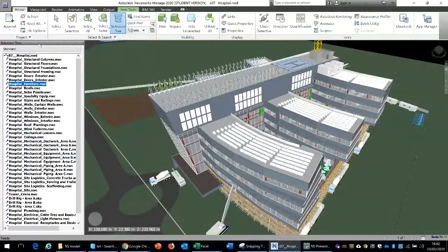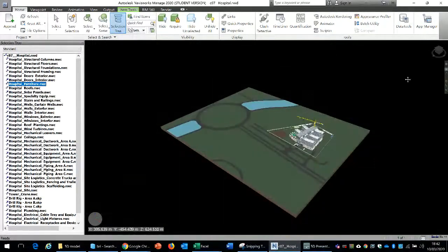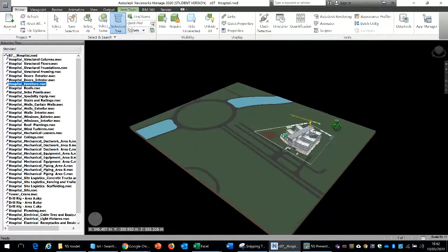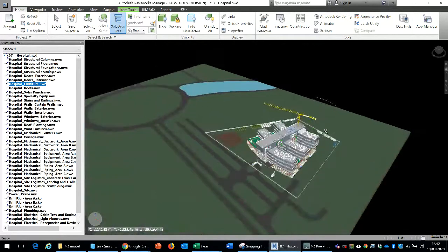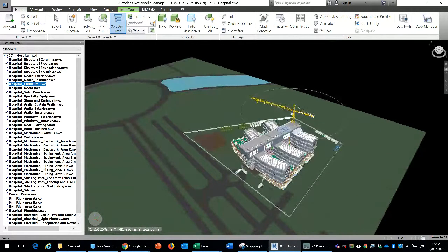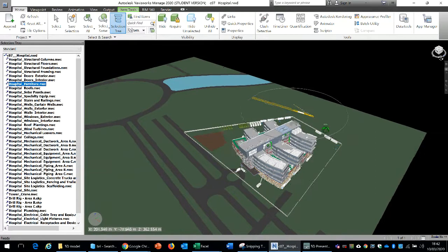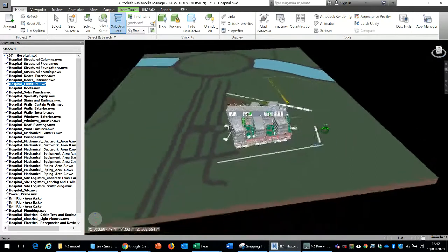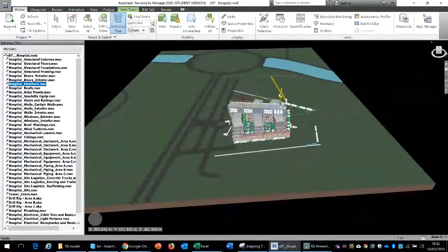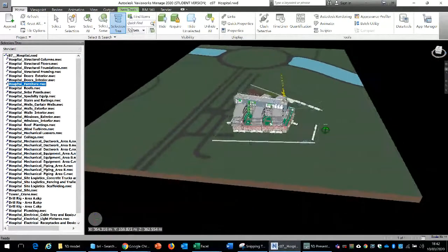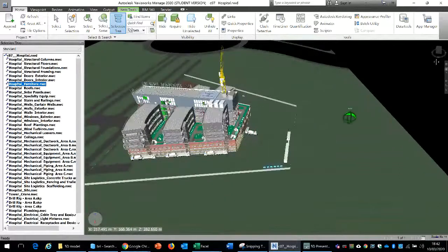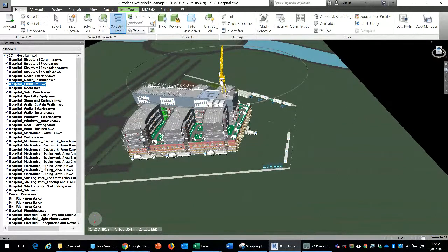Now, if we look at some of the features, as is the case with most BIM software tools, there are a great deal of ways to manipulate the model in different ways. So for instance, there's a home tab, then on the top there is a cube, which basically allows us to turn the model 360 degrees, or there is this sort of a cube here, which allows us to have a predefined view.